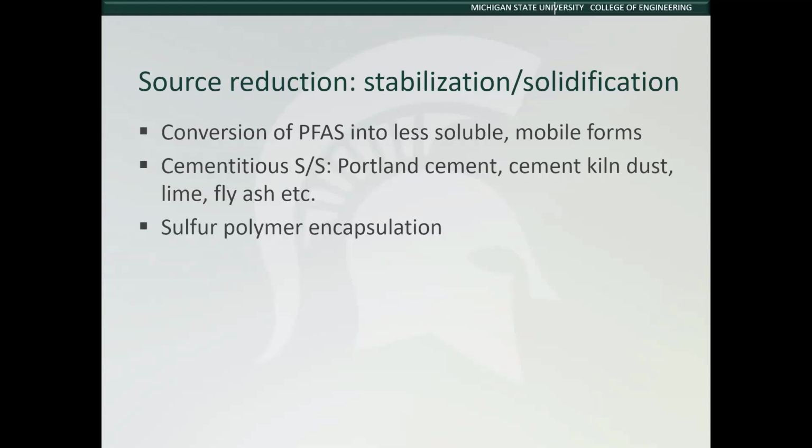Sulfur cement has a number of advantages over Portland cement. Sulfur concrete has higher compression and tensile strengths. The full strength of this material is reached in hours rather than in weeks. The process has been widely used for radioactive, hazardous, and mixed wastes. The loading rates tend to be greater than that for the cementitious processes.